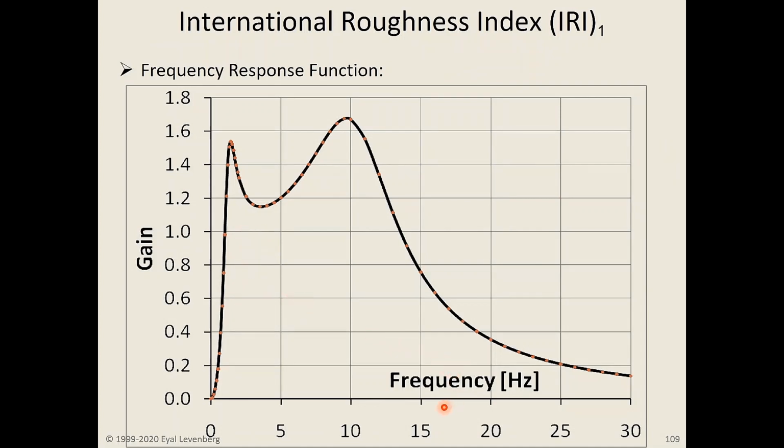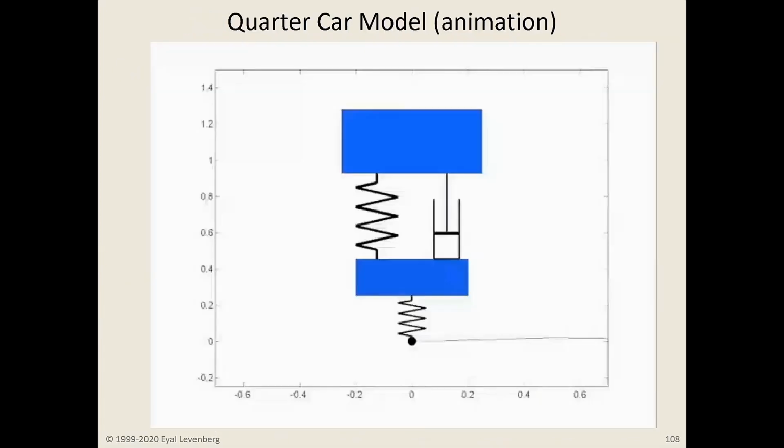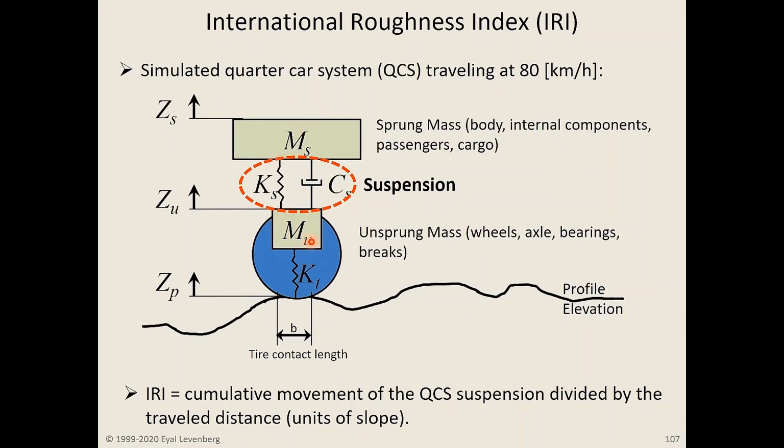Injecting a pure sine with a certain frequency and amplitude as input is a very common method to interrogate linear systems, like the quarter car model simulator. The reason is that after a steady state is reached, all system components vibrate at the exact same frequency as the input frequency. The amplitudes of the different components would most likely be different, and there could be some phase lag between the input wave and the movement of the different masses. But the entire system will also move in a pure sine wave way, and share the exact same input frequency.